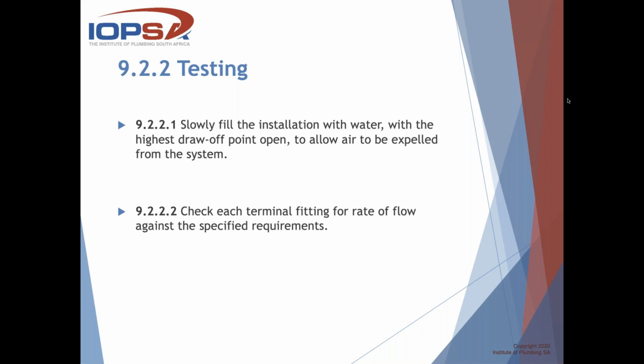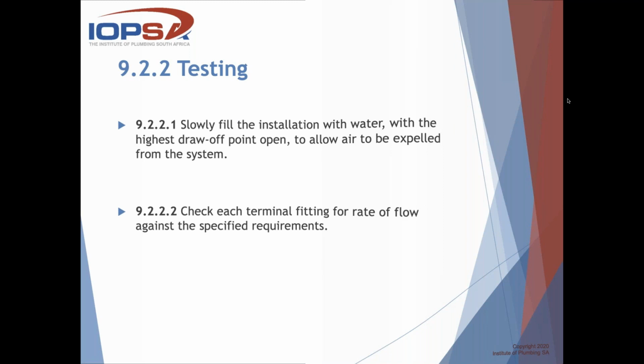And then we can use equipment. Rothenberger makes them, and Ridgid is the green one, the bottom. And these are the instructions of how it's done. It says slowly fill the system, walk around the system, check for leaks, leave it to stand for 30 minutes, attach the hydraulic pressure tester, and they all work on basically the same principles. You even get electrical ones as well. Pump the system up to 1.5 times the working pressure. Leave it pressurized for 1 hour, check for any drop in pressure, and rectify any leaks. So that's exactly what the standard says.